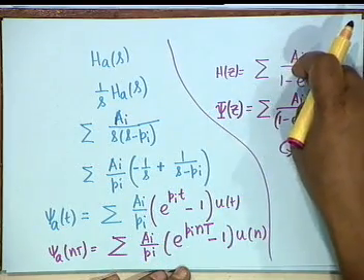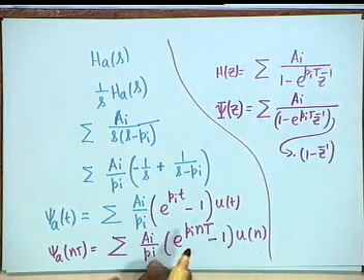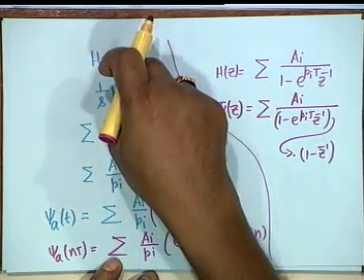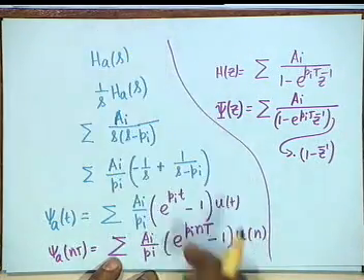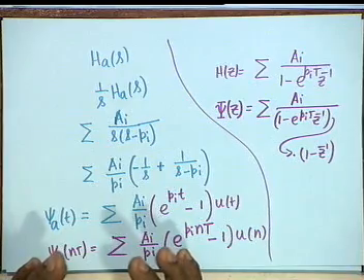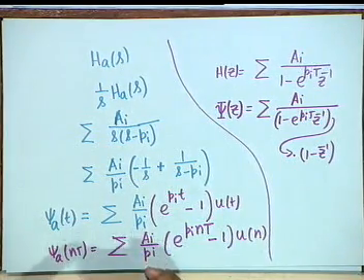We want to find out the unit step response of this. We have already found the unit step response of the filter derived from the analog filter, and we want to compare the two. If they are identical, then step invariance is implied by impulse invariance.